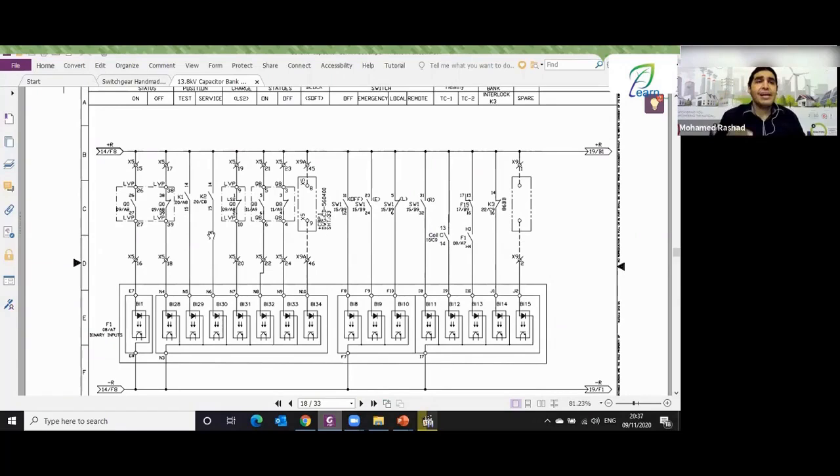The third thing is that it should receive a set of statuses to create an internal circuit for opening or closing. So when I come to close it, I should tell it not to close because the spring is not charged, or the gas pressure is low, or the breaker is not in the trip position or trip out, or, for example, the protection is not reset.